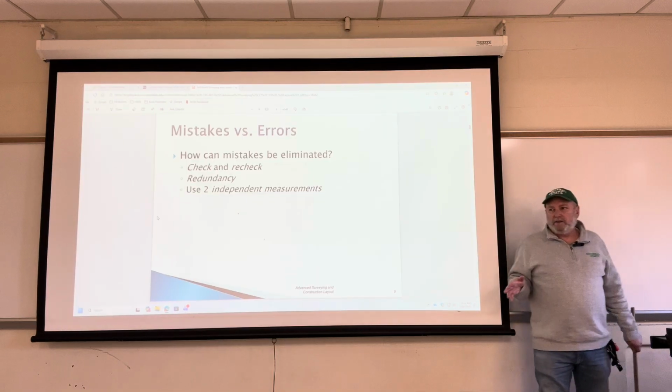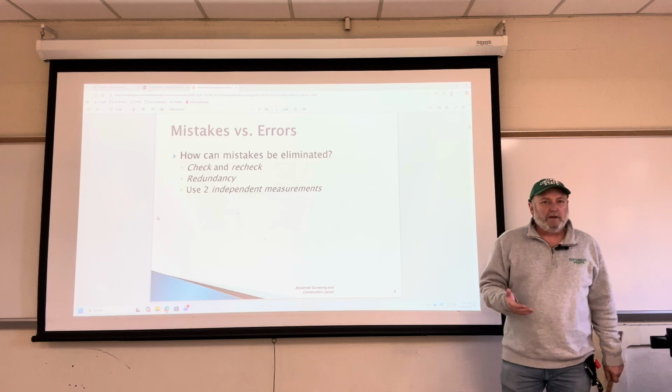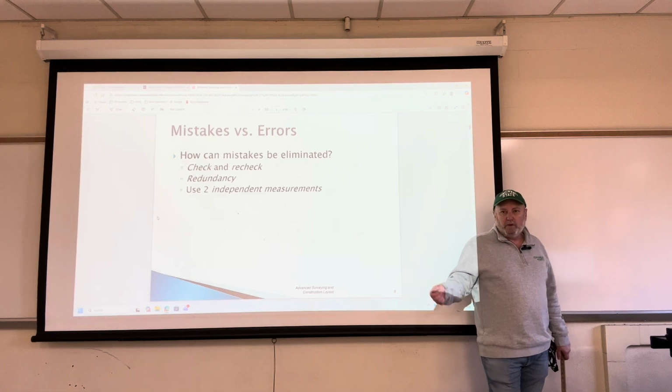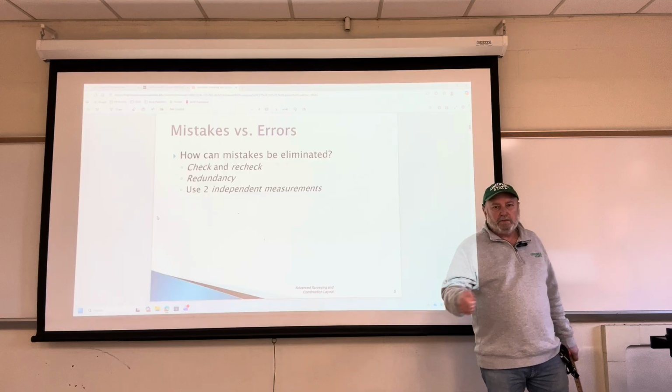Changing technologies would be a good way to say it. So if you lay something out with your GNSS receivers or your total stations, pull a tape measure out and pull some distances between to verify.